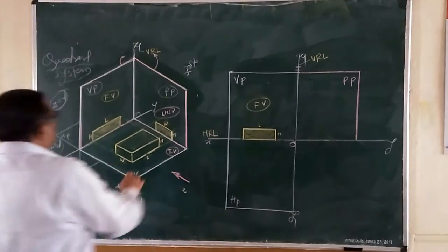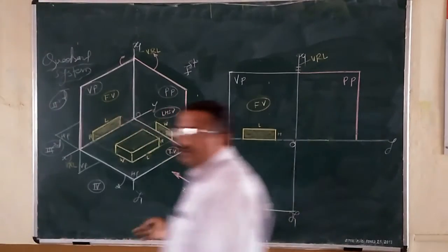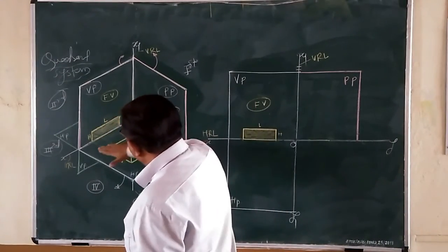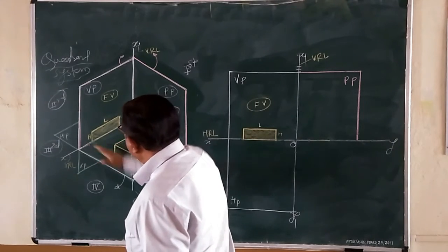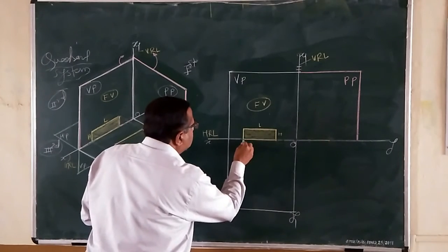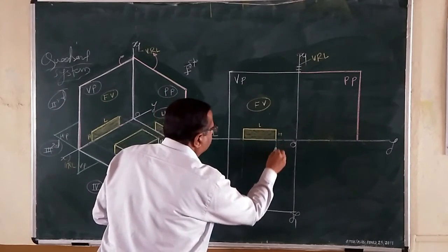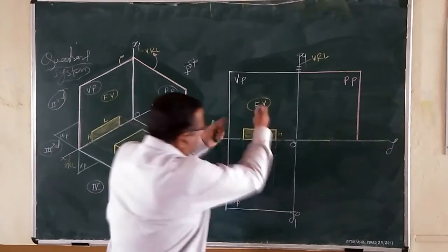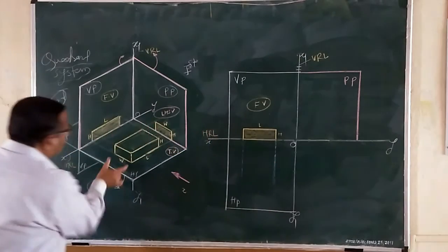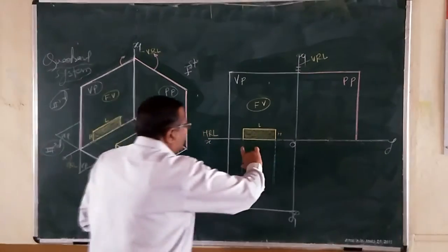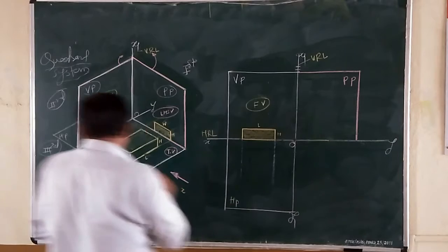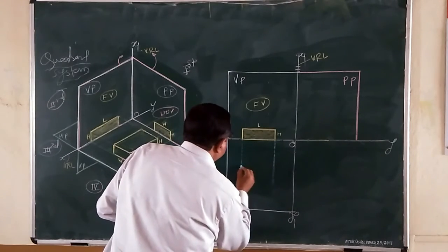Now, next, the top image that we will get over the horizontal plane, that we are tilting in the downward direction. So just below this, you see these projectors will be in line with this vertical line. So naturally you have to extend these lines over. So automatically the length has been carried forward. So just pick the width by compass and transfer it anywhere on this line. Conveniently, any distance you can maintain here and transfer this width here. This much is the width.